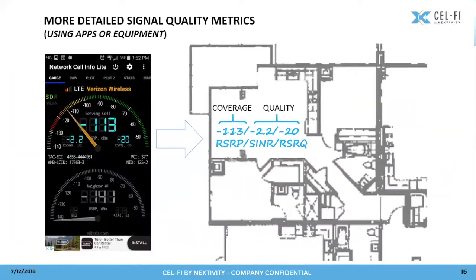When measuring, people have fancy tools, etc. Remember I talked about not using RSSI, because with RSSI you can have a stronger signal because you have interfering cell sites. All of that energy gets amassed together, and your RSSI meter shows, hey, you've got lots of donor signal. But it doesn't tell you that it's actually completely pilot polluted and has massive capacity issues, etc.